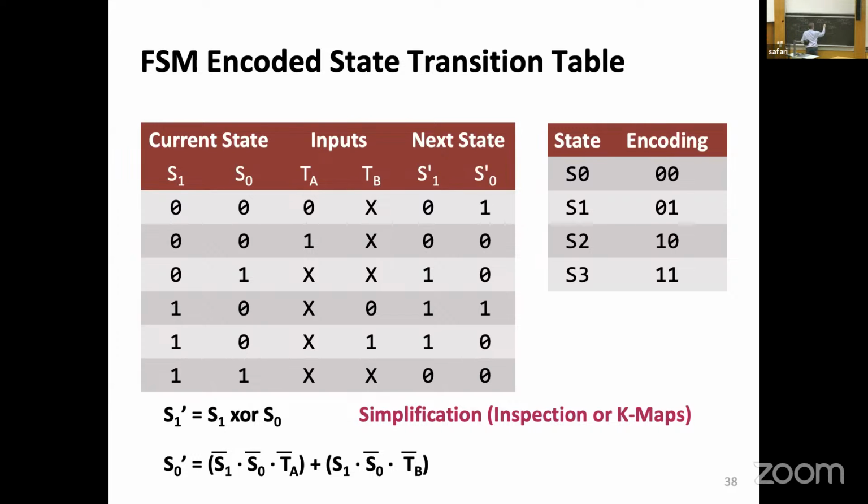And where am I storing it? Well, we already know that this will be a flip-flop, a D-type rising edge flip-flop controlled by the clock. And we might even have a reset. Let's write it here. There's a tiny reset here. Okay. The job of this thing is knowing what state we are in, knowing what the inputs are, trying to figure out what the next state will be. There, we can write a truth table. The truth table will reveal itself to be a combinational circuit, and we can do that.